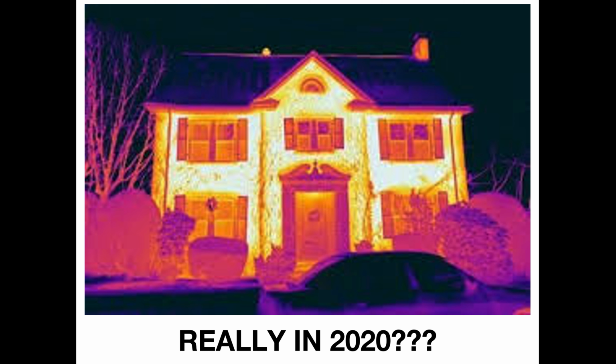Now, if I go back to the 10 air changes per hour, let's just do a basic calculation. If you've got a 2-bedroom flat, and we'll call it 100 square meters of space, that's quite a big 2-bedroom flat, normally about 60 to 80. But if we've got 100 square meters of flat, we've got a 2.4 meter high ceiling as standard. So that's 240 cubic meters in that property.